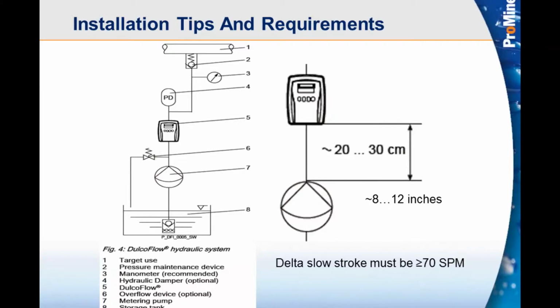So you can exceed that, that's not a problem, but we want to regulate it to a minimum of 40 psi in most cases. We can work some applications below that, but we would have to take extra care and trial that before we commit to it. So just be careful. Again, we want to regulate the back pressure. When we regulate the back pressure, you see that M6 is now a pressure relief valve. So always take that extra safety step.